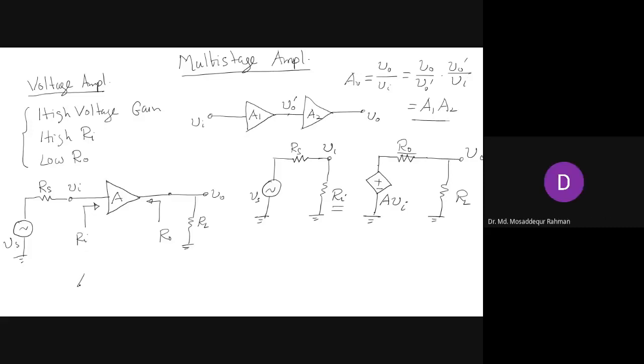No questions. So, overall gain, actually A is the gain of just the amplifier, right? Overall gain is V0 by Vs, and we can express that as V0 by Vi times Vi by Vs. So first we discuss Vi by Vs, which we get from this circuit, and this is obvious.